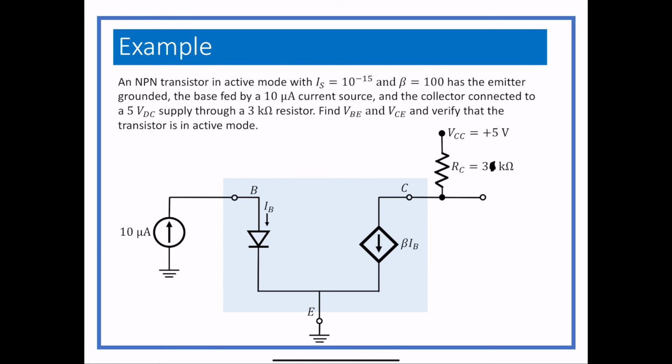We can replace 100 IB also and put VCE and VBE in where they would be. So VCE is at the output between the collector and ground, and VBE is at the input between the base and ground. And then we can replace that value of beta at some point with 100. There we go. So now this is the full model. It's got everything that we were given, and then we can just go ahead and figure out values. So we can start with finding IC.